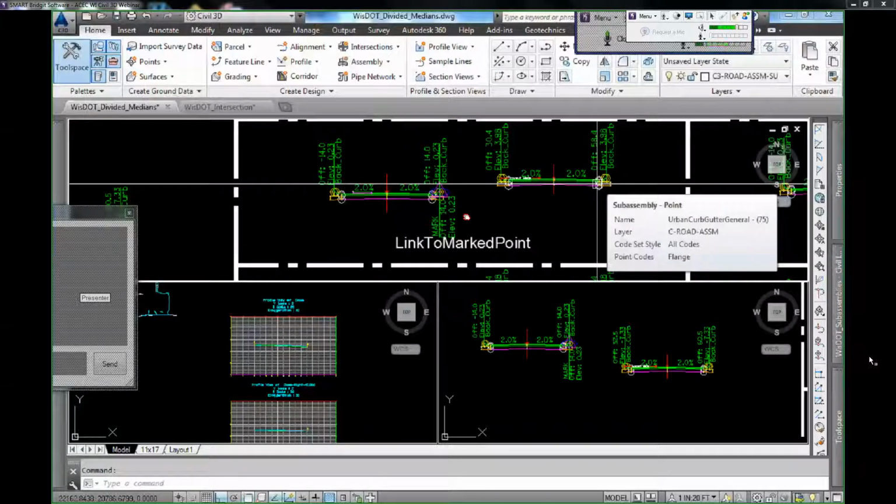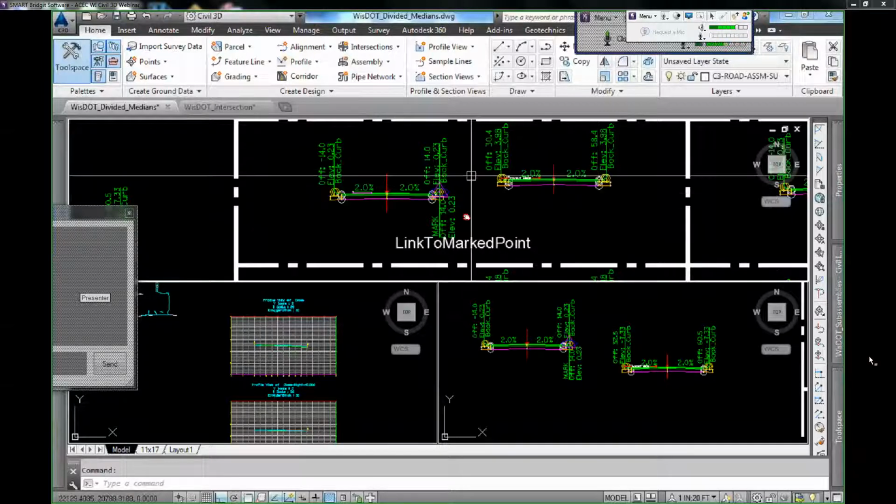Now, what I'm going to show you eventually is doing an intersection. Using an intersection is going to force me to have your normal centerline alignments, okay? I wanted to do this because one thing about the intersection tool is it can build intersections quite quickly, so for large intersections it's really nice. What I like to do is build the intersection first, then come back and fill in the regions in between, from intersection to intersection. So I'll let the intersection figure out all the oddball stations for me, and then I'll fill in the gaps later on. I'll show you that in a minute too.